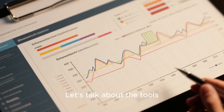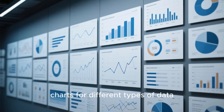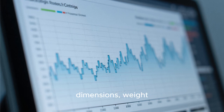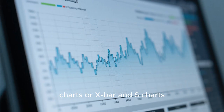Let's talk about the tools. The most famous are the Shewhart control charts. There are different types of charts for different types of data. If you're measuring continuous data like dimensions, weight, or temperature, you'll likely use X-bar and R charts or X-bar and S charts.